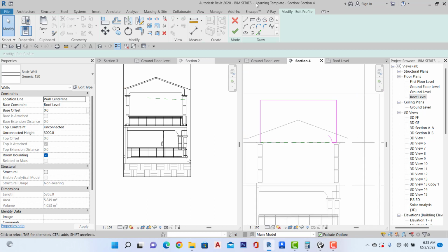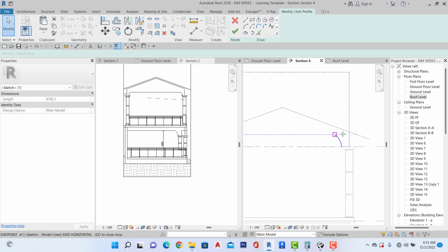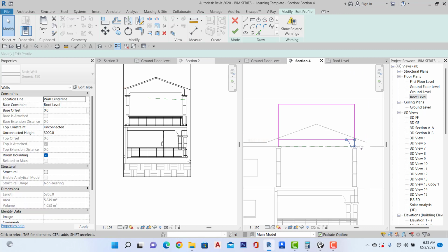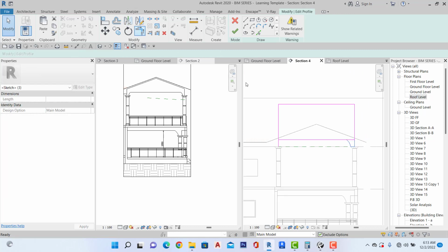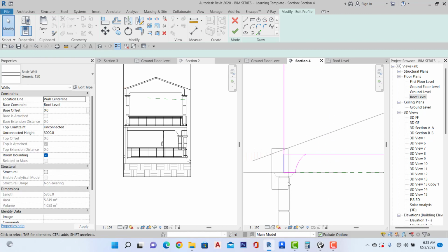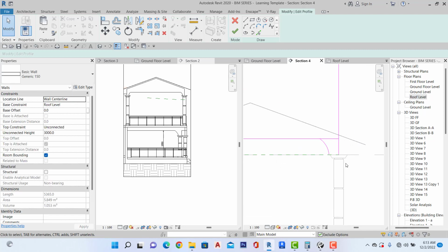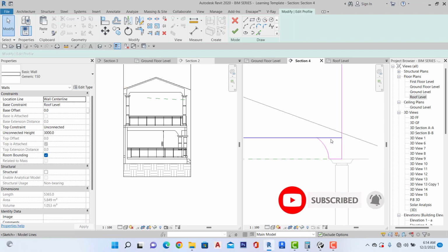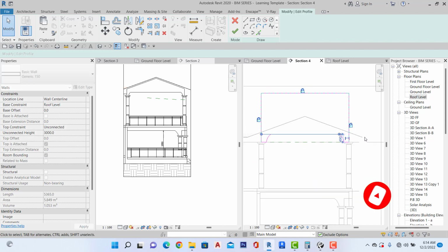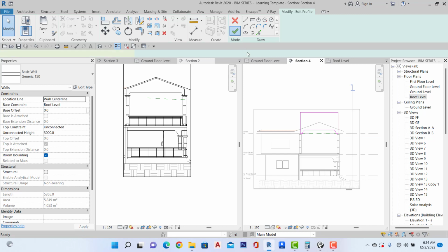So after doing this, now you can draw a line here. If you like better still, you can extend this line here. Then you mirror out so that I had a midpoint. So you can select this line also and delete, select this line. Oh no, just this one and delete. After that you can join this one to the endpoint, then you do finish.